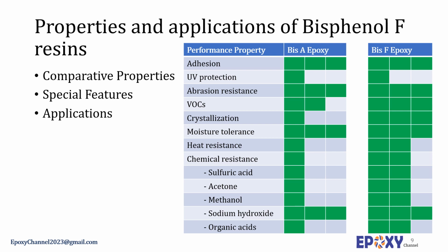Regarding the curing, Bisphenol-F epoxy resins react with a full range of epoxy curative, and the whole spectrum of curing agents can be employed. When Bisphenol-F epoxy resin is cross-linked with appropriate curing agents, superior mechanical, adhesive, electrical, and chemical resistant properties can be obtained. Generally speaking, the performance of Bisphenol-F epoxy resin is comparably better than the performance of Bisphenol A epoxy resins.